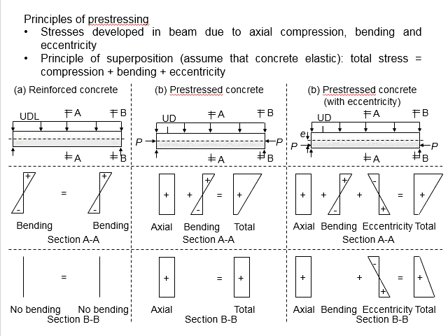Based on the principle of static equilibrium, you are able to determine its shear force diagram and bending moment diagram. Now we will need to determine the stress in the member. There will be two critical parts of the simply supported beam, which are section AA at the midspan and section BB at the support.